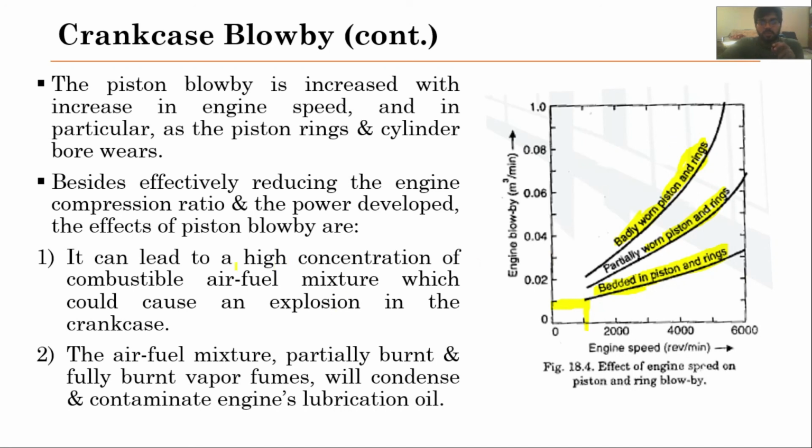So what are the disadvantages of it? It can lead to a high concentration of combustible air-fuel mixture in the crankcase, which could cause an explosion. Not only that, the air-fuel mixture, partially burnt and fully burnt vapor fumes will condense and contaminate the engine lubrication oil.